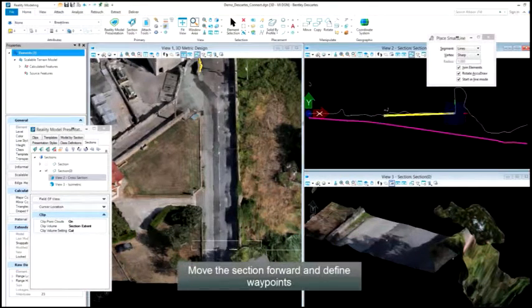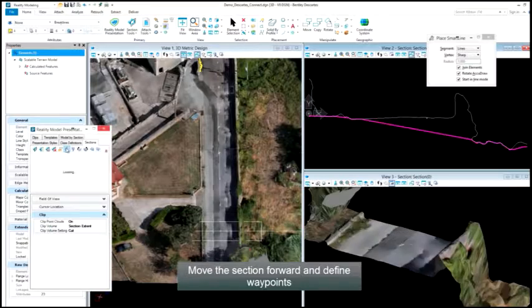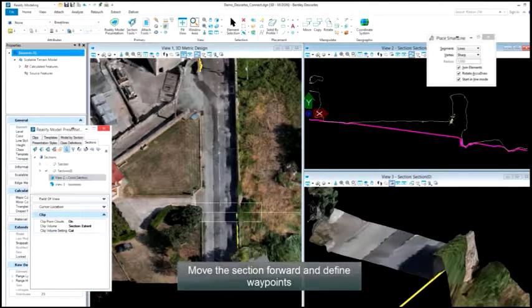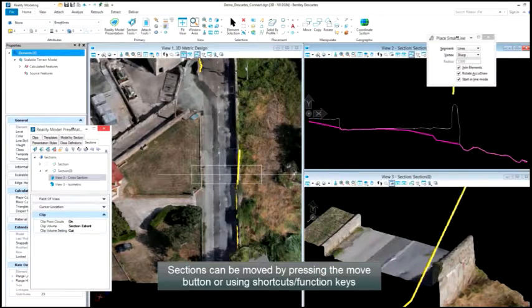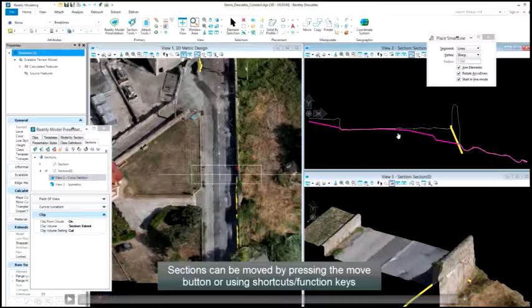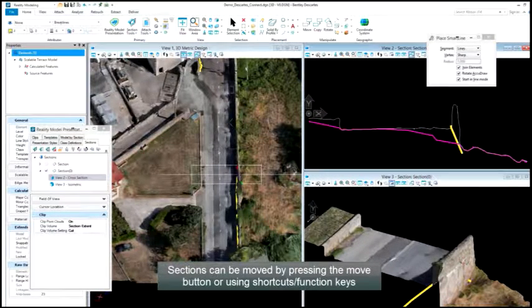There are utilities for separating the mesh, breaking it up into various surfaces. You can add break lines and things of that nature. You can segment aspects of the surfaces and classify them as new objects. So that when you bring it into the design environment, these things are not just a pretty picture or a mesh. You can actually know that this is a sign, this is an abutment, this is a pavement, and so on and so on.